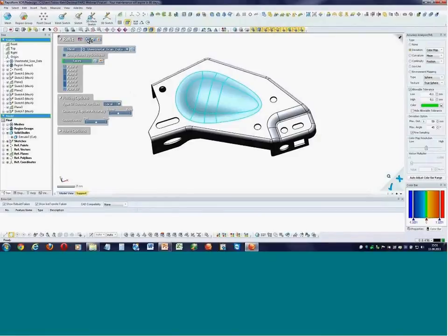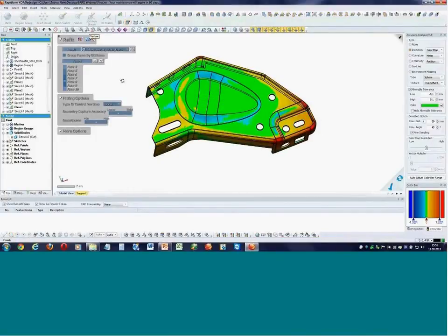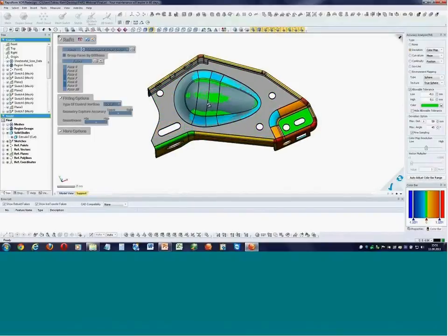And then you can apply a preview, and then the faces will be attached to the scan data. So it is more or less combining CAD operations with mesh fit operations. And this is the result. So the deviation is minimized, and your CAD model is more reflecting the actual shape of the scan data.